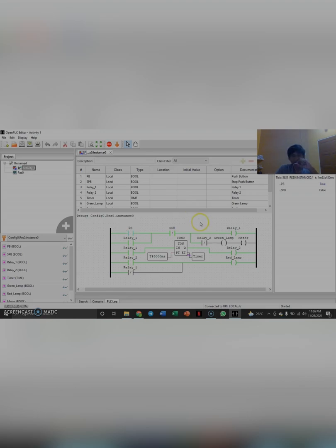But even though the red lamp is turned on and the motor is turned off, at this line there is still a current, so we need to change the push button in the initial condition to normally open. And this is the stop push button. Its purpose is for emergencies on the conveyor, and it will force the motor to stop automatically.